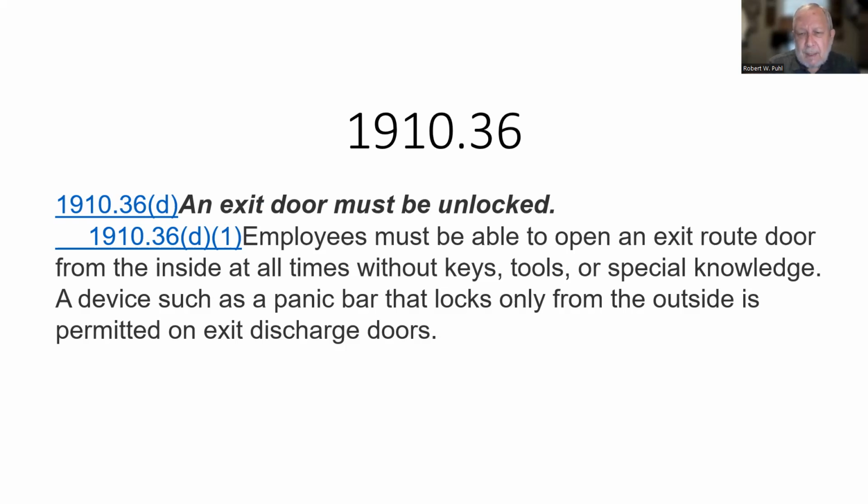So the panic bar with a lock is probably the most common of the standard doors. I know that the college has them too. When the door closes, it's locked from the outside all the time. That's fine, but you've got a panic bar on the inside, so you push the panic bar and you're out the door. That's probably the most common and probably the best kind of exit, in my opinion. Now, there are devices, or people can put stuff in that panic bar, that don't allow it to open, and that is not right. That's not legal.